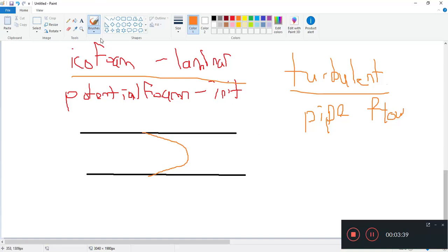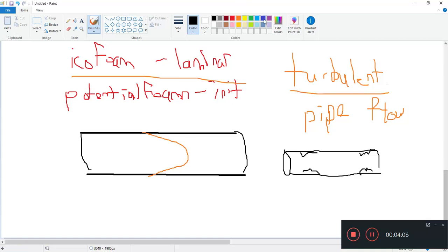So there are a number of problems that we want to address before we start turbulent pipe flow proper. Firstly, we know that in our snappyHexMesh, we had some really rough edges around here. If you've been watching the last video, the meshing process has left some things out. And we know the way to solve that is with a relatively high refinement level. Let's say a refinement level of 5 to 6 will make sure that there's no such thing on the surface. It will make sure it's very smooth.